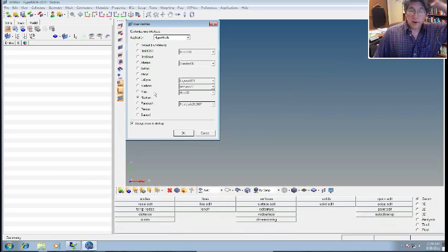And now this is the type of window you'll get. All right, the first thing that pops up is this user profile window. This is pretty important. This is what's going to say, am I making a finite element model to run in Nastran, LS-DYNA, ANSYS, Abaqus, and so forth? It changes the interface slightly and the options slightly depending on what solver you're going to use. So we're going to use Nastran. You click on Nastran if it's not the one that's clicked, and then you hit OK.